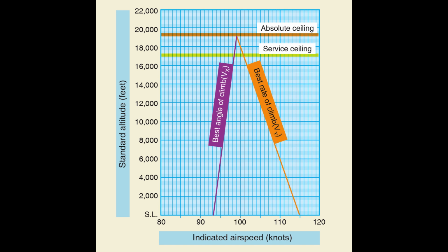Increased lift will generate more induced drag. That increase in induced drag is why more power is needed and why a sustained climb requires an excess of thrust. For practical purposes, gravity or weight is a constant. A vector diagram shows why more lift is necessary during a climb, as the vertical component of lift generated from the wings is no longer perpendicular to the wings and adds to drag. The total vertical force is increased by adding a vertical component of thrust from the power plant, and the power should be advanced to the recommended climb power.